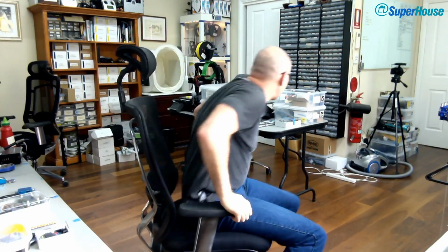Oh, that's a good point. John Ford said, can't clamp over live and neutral because they cancel each other out. Yes. So if you are using something like this, then you can't just get a mains power lead and clamp over the whole thing because you'll get 0. In fact, I'm going to unclip my microphone here. Luckily I remembered that and I didn't walk away and rip the computer off the bench.